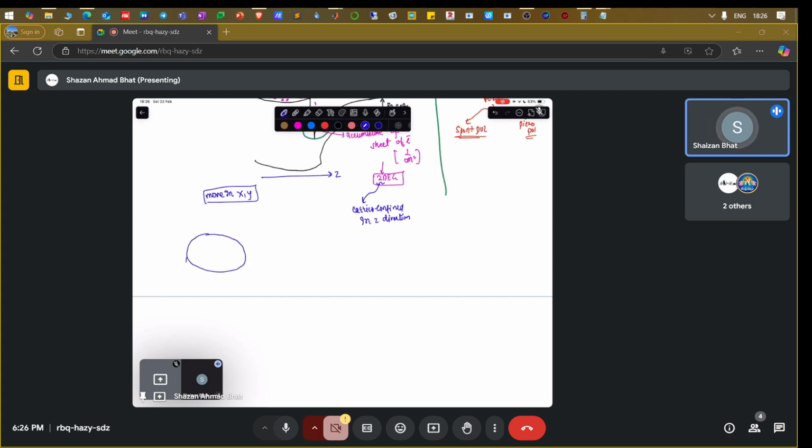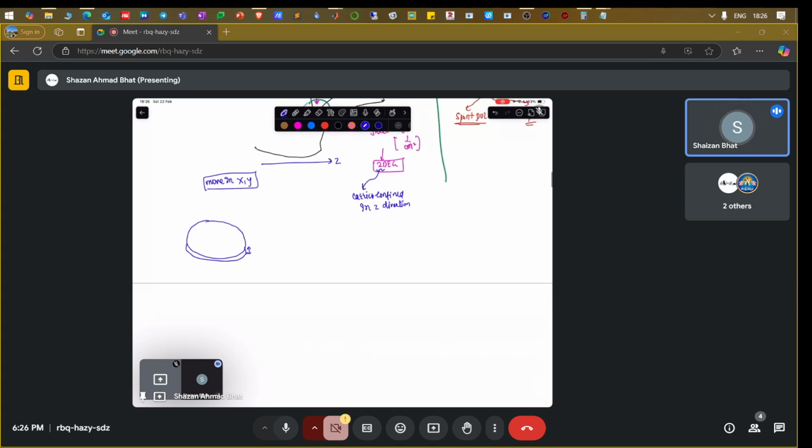And this wafer has a certain thickness, you know it. This thickness is very small because this is the growth direction. You grow it from bottom to top. You start growing certain layers. First you have one layer, then you have another layer, then another layer. So that's how you grow the heterostructure.